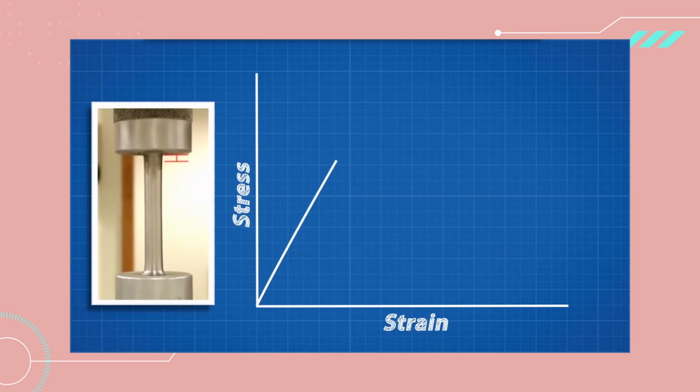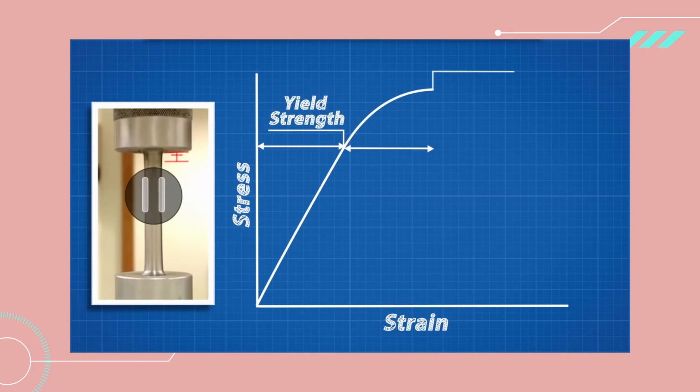As the stress rises, the material begins to deform. This initial linear region is elastic deformation. That means that if we remove the force, the material regains its original shape. Think of how a rubber band can be deformed hugely and still come back to its original shape. The end of this linear elastic deformation is marked by the yield point. From here, any additional stress will cause permanent deformation. This is called plastic deformation.